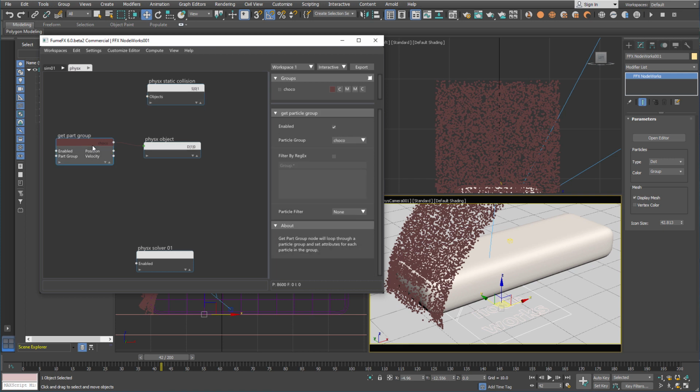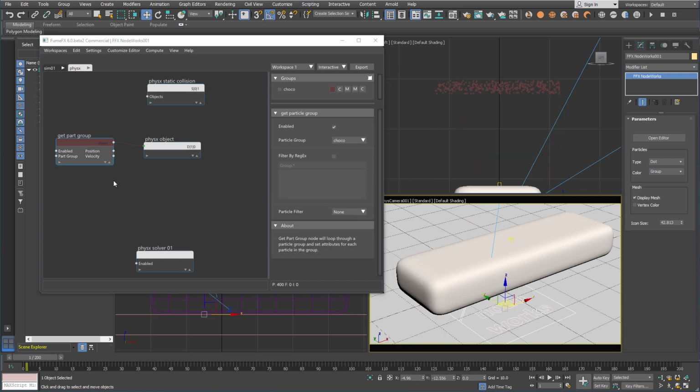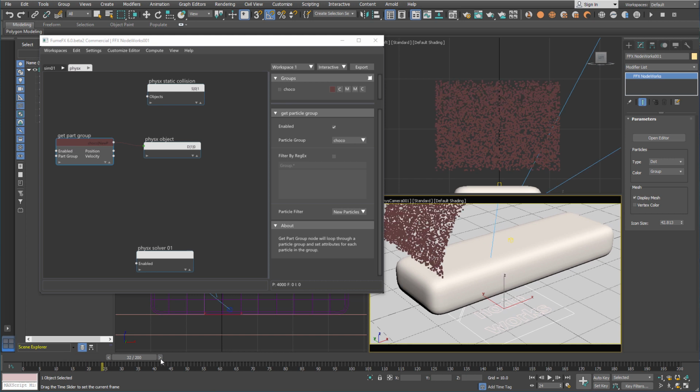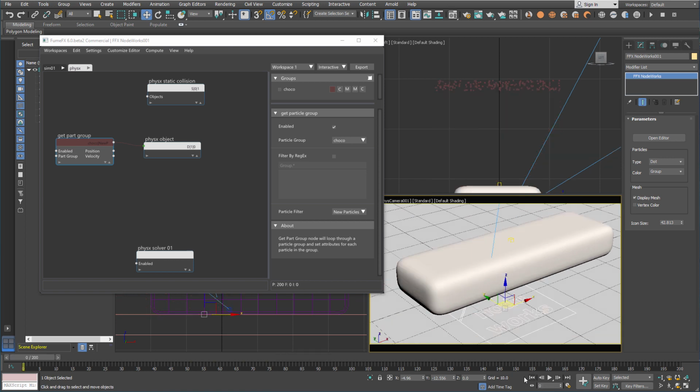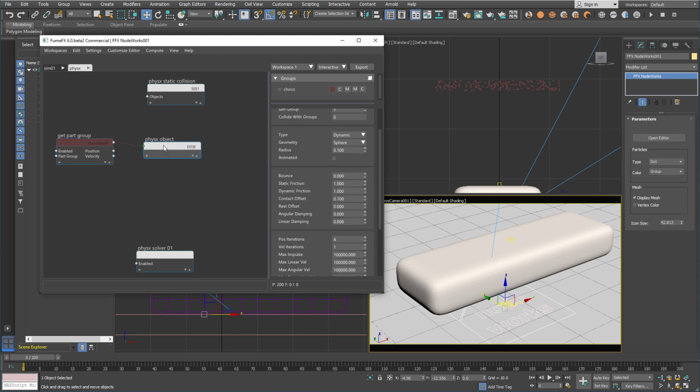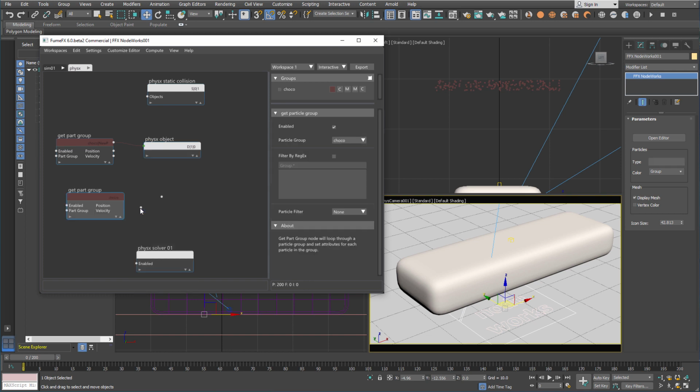One thing I forgot to mention here is that we need to add those particles to the physics objects only when the particles are created, not for each frame. So only when the particle is created is it going to be pushed to the physics simulation engine. So this filter will just output new particles through this connection to the physics object that will add those particles to the solver.